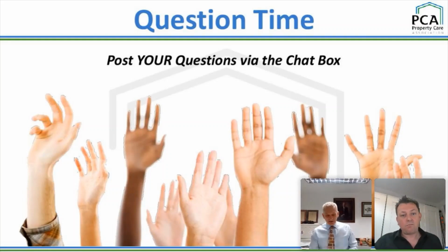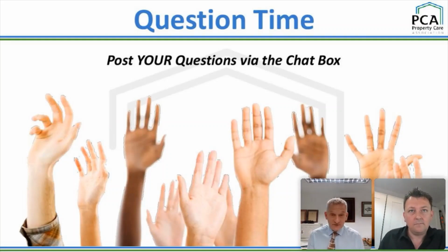Well, the thing is, at the end of the day, there are guidance notes on this. But with a timber frame, and this is a remedial perspective, not brand new, the ties must go into the studs, not just into the sheathing. I have done one job where specifically they were put in the sheathing, but you need a very high density for that because the ties won't be able to do much work individually. You might only get 500 newtons on a tension test on that. And that can slightly defeat the object sometimes, depending on the design, because timber frame and cladding move relative to each other in all planes. So you don't really want something too rigid or too many things crossing the cavity.